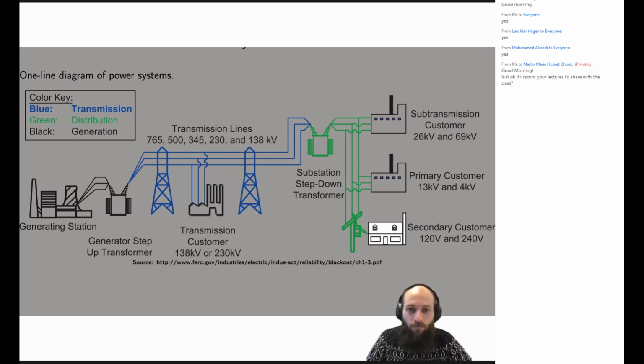And if we are using low voltage and high current, that will give us a lot of losses, because we have ohmic losses that are equal to R times I square. So what we want is to transform this electrical power into high voltage power and low current.